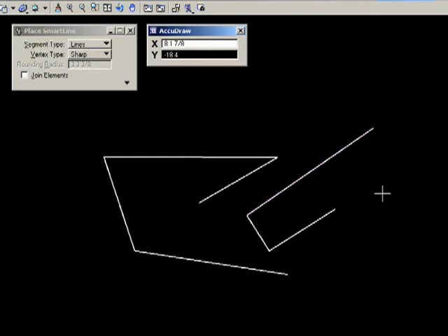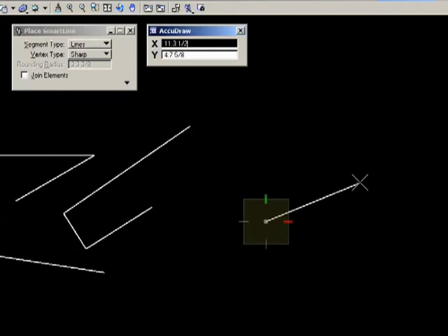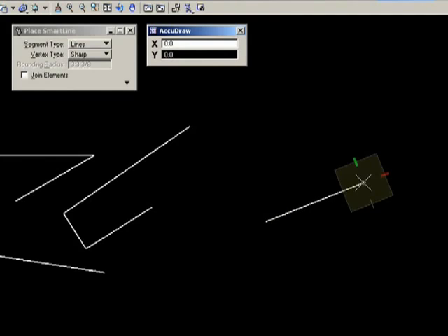Right click. What's happening here is that Microstation is anticipating your next move. And it's assuming that you will likely want to draw at right angles to the previous line. So it aligns a compass with the previous line, so you can quickly lock to one of the axes to place the next data point. If you are drawing in a rectangular fashion, you can place right angle corners very quickly. If your next line is not at right angles to the previous line, you can simply drag the line away from the axis to place a data point.